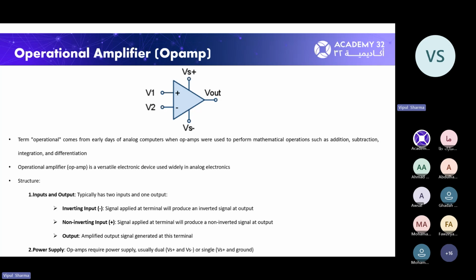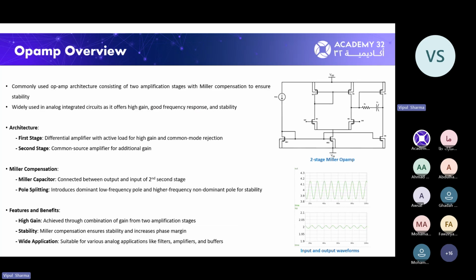If you use such high power supplies with the op-amp in open loop configuration, then the power dissipation through the op-amp will be very high. So practically, whatever benefits you want to achieve, whether you want to use it for these operations, or as an amplifier or buffer, most of these are beneficial if used in feedback configuration. And with feedback, there are other practical gains achieved with this op-amp. That is, the bandwidth of this configuration increases with the feedback. And then there are several other benefits also.